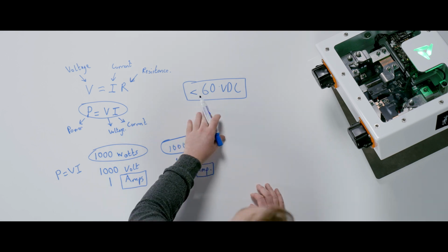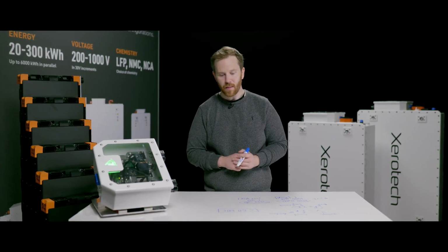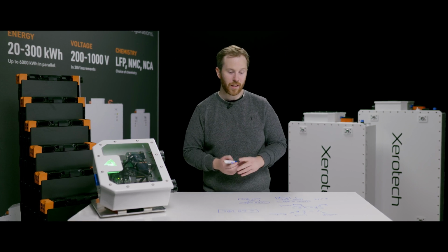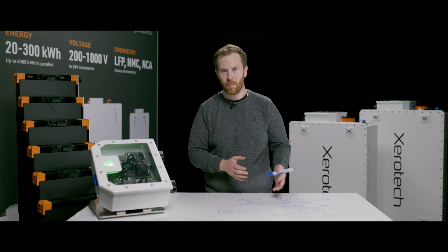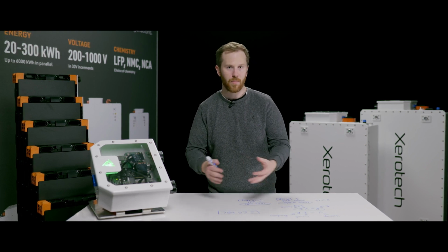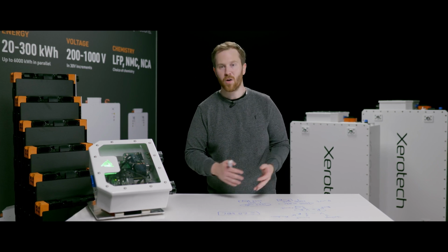Whereas if you see a high voltage battery system that's over this threshold or over a few hundred volts, all of the connectors are orange. You can't touch any conducting components because you could get an electric shock from that system. So that's the big difference. And I suppose there's an added cost of going to higher voltages. The conductors all have to be protected. There's more advanced safety and protection systems, but it comes at big benefits of being able to deliver much higher powers throughout the system.